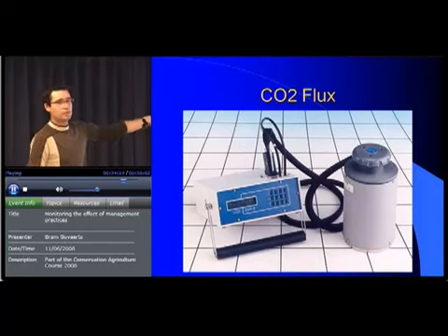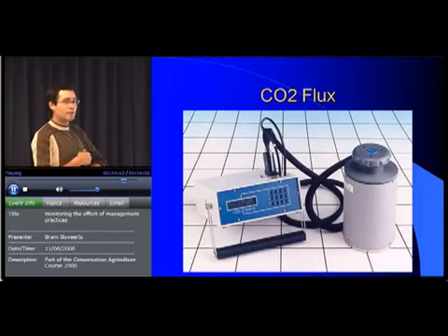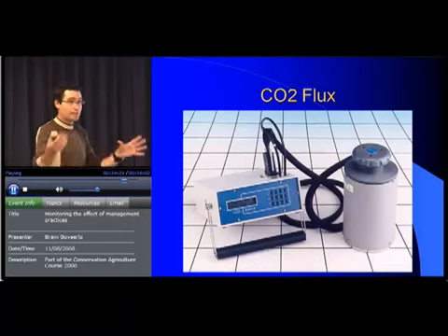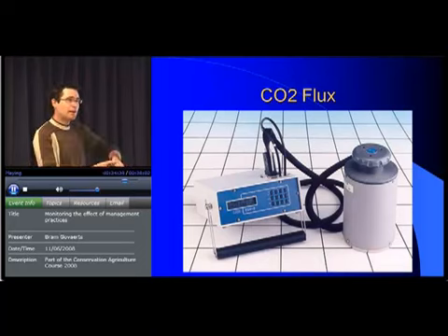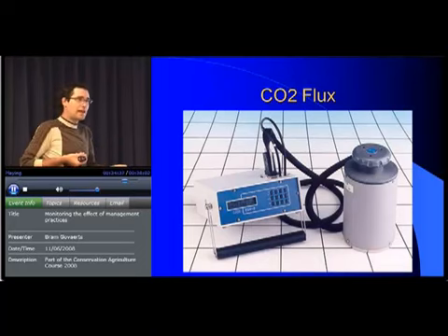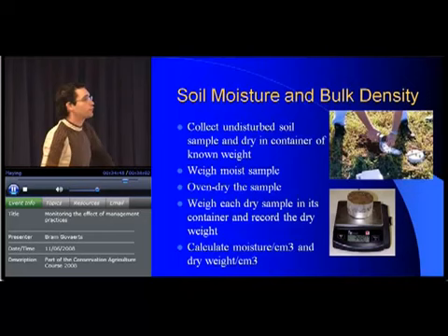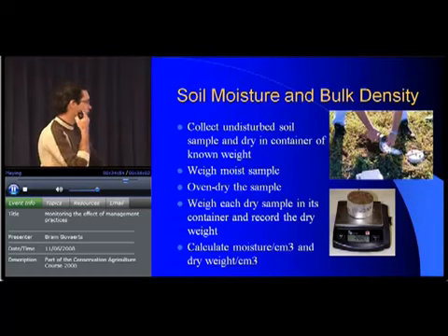Now there are even more fancy ones. What we are going to see in the field today also is we now have chambers that were designed by a student of mine. I didn't do it. A student, Leonardo Coutinho, he's from Staff, and same thing, he designed the chambers himself. We let them make by in a local shop, and what we do there is we just extract with a needle, we extract the air, and that we analyze for trace gases in a chromatograph. Right? This, of course, you know, soil bulk density, soil moisture, just by gravimetric and with the soil density. With the bulk density, so you can turn it into volumetric.